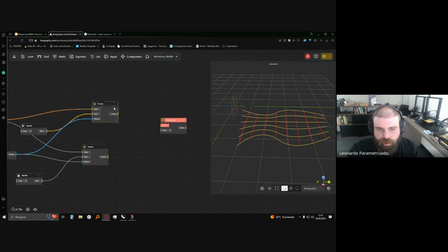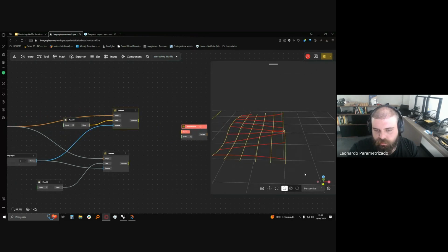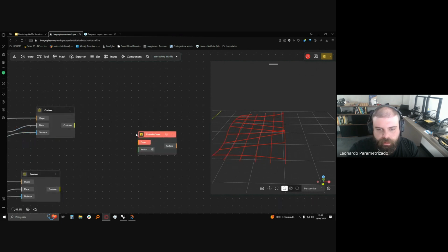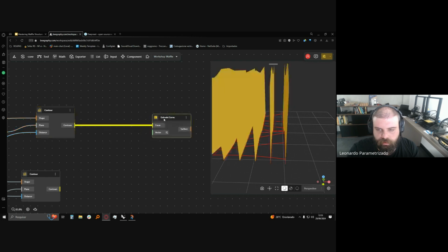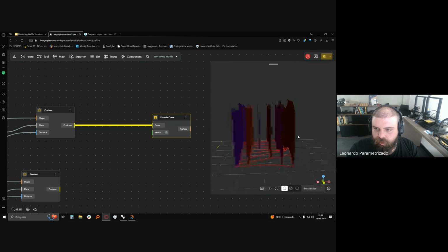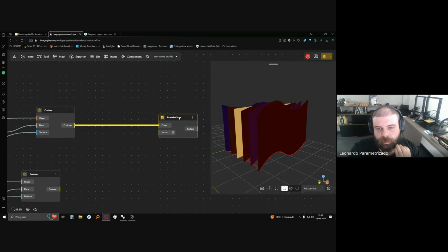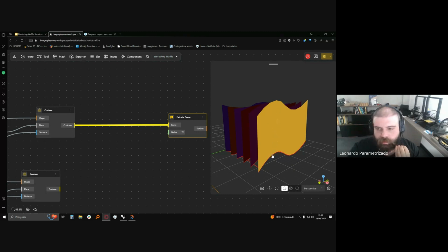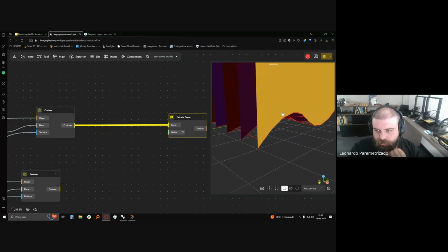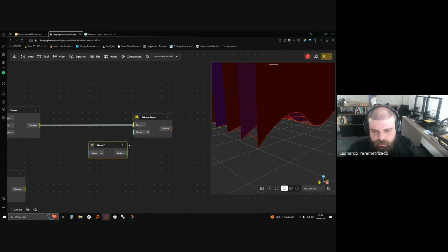So this is my output for the curves in the X direction. I can simply get these curves and put them in the extrude. As you can see, we are starting to have the surface, the area of these beams. But the problem is it's going up now. We need to go down here in our surface. So I'll be using, again, the vector Z here.